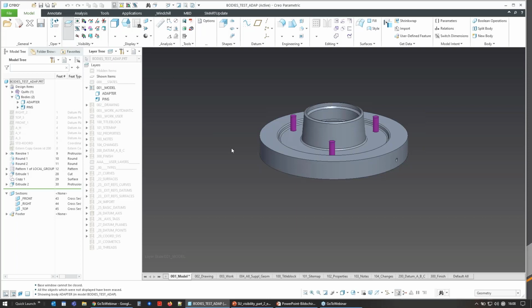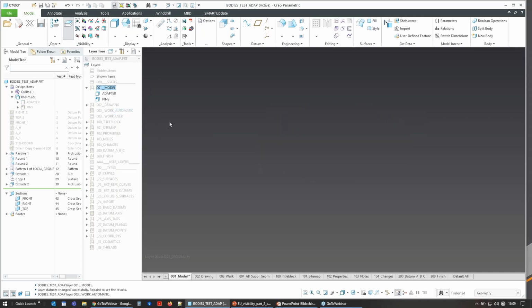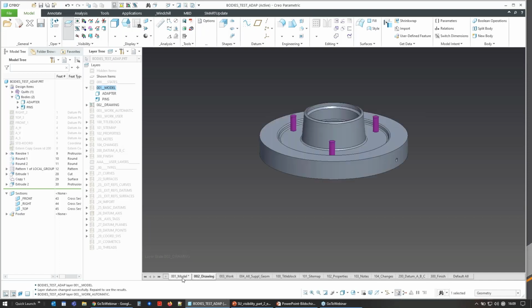And yeah, if I want to blank them, right mouse button, hide, and they will disappear. So this is what I can do for all the combined states. If I'm switching back to another one, going back, it's visible again. This is because I have not saved my layer state. So I think the first scenario is very easy, but you have to put the things on a layer because otherwise you wouldn't be able to blank anything.